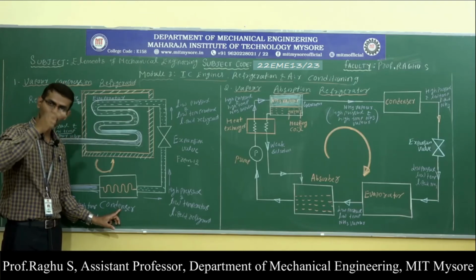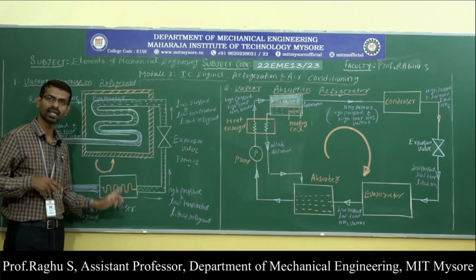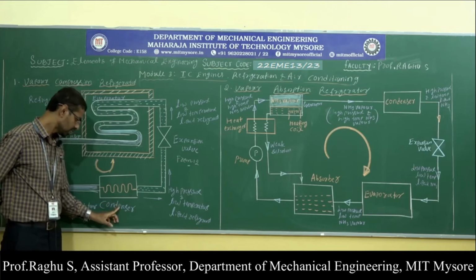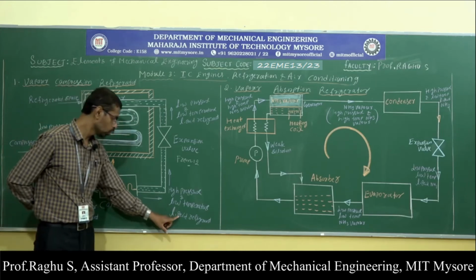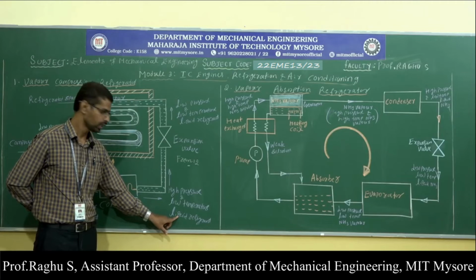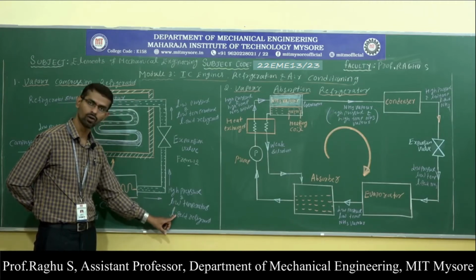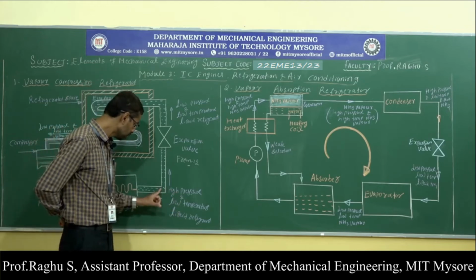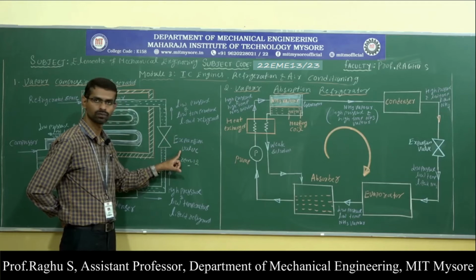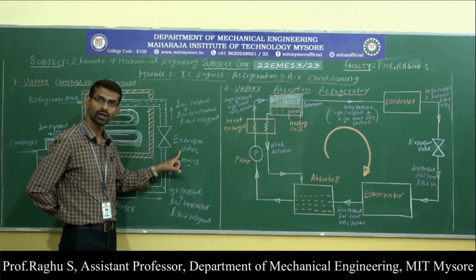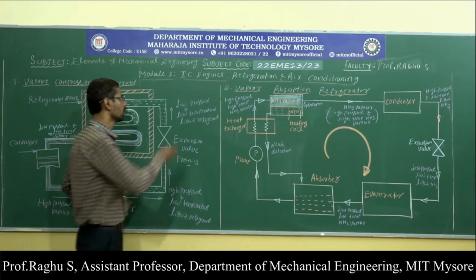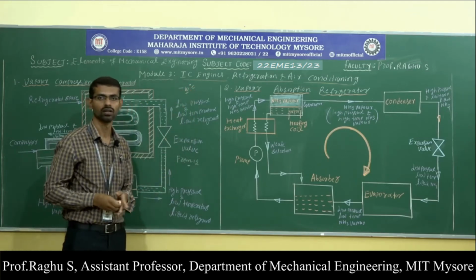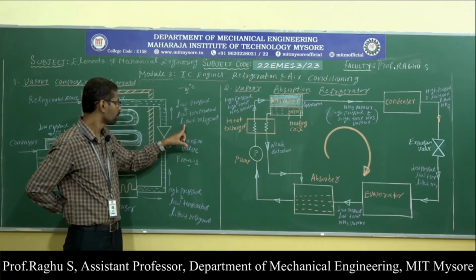Condenser consists of cooling coils which are arranged in U-tubes. Condenser coils are located just behind the refrigerator. Condenser converts the vapor form of refrigerant into liquid form with a high pressure and low temperature. Now, high pressure and low temperature liquid refrigerant enters into the expansion valve. In the expansion valve, expansion of liquid refrigerant takes place. Due to expansion process, the temperature and pressure get reduced to lower value. The temperature gets reduced to minus 10 degrees centigrade. Now, here we have low pressure and low temperature liquid refrigerant.